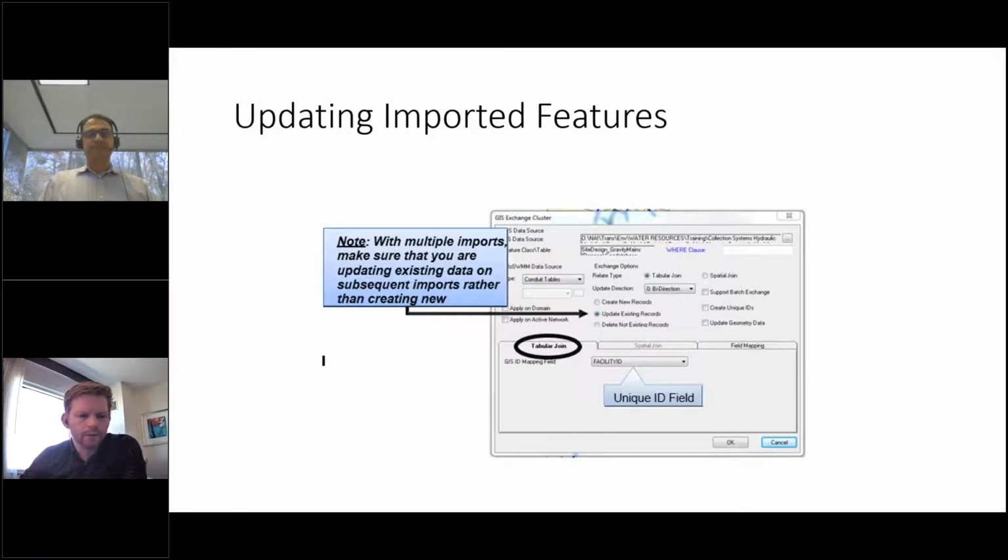And then also a note on the unique ID: it is kind of the record keeper, but underneath utilities and change ID tool, there is an option to be able to change those from the existing old one into a new ID. So there is a possibility of changing that, whether it's that convenient to have to key in all that information. It could be kind of a pain to do it within the change ID tool, but at the same time, it is a capability. But yeah, that's all I got.